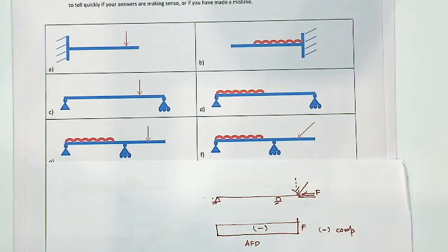Two rows back. Yeah? I also wanted to ask about axial force diagrams, but how do you do axial force diagrams where there are two or more? You have to start adding up algebraically. If they are going in the same direction, you add them up. If it is opposite directions...